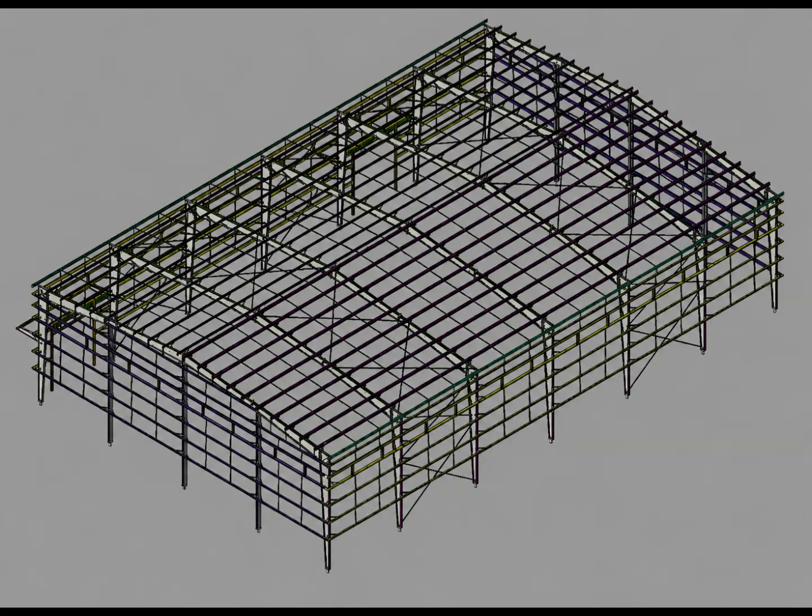Finally, remember this simple workflow: drawing, member identification, location, connection, 3D coordination. If you follow this sequence carefully, even a complicated PEB structure becomes much easier to understand. The goal is not simply to recognize a steel member. The goal is to understand the complete structural system.